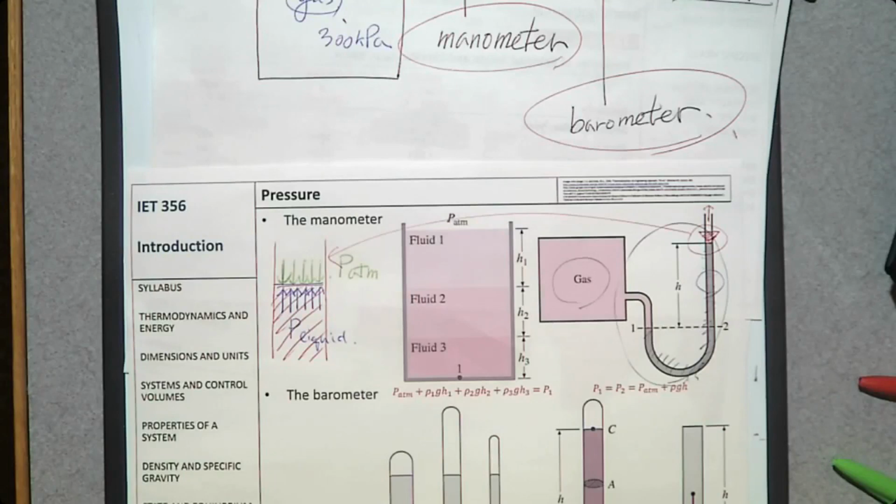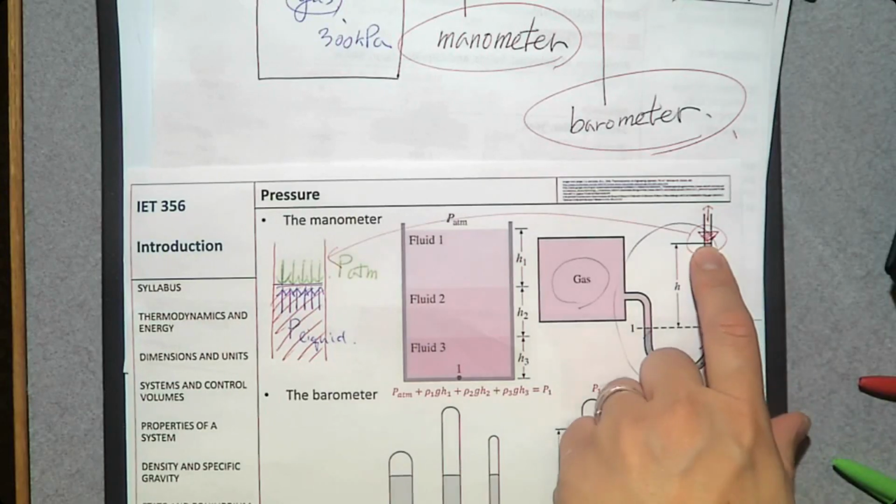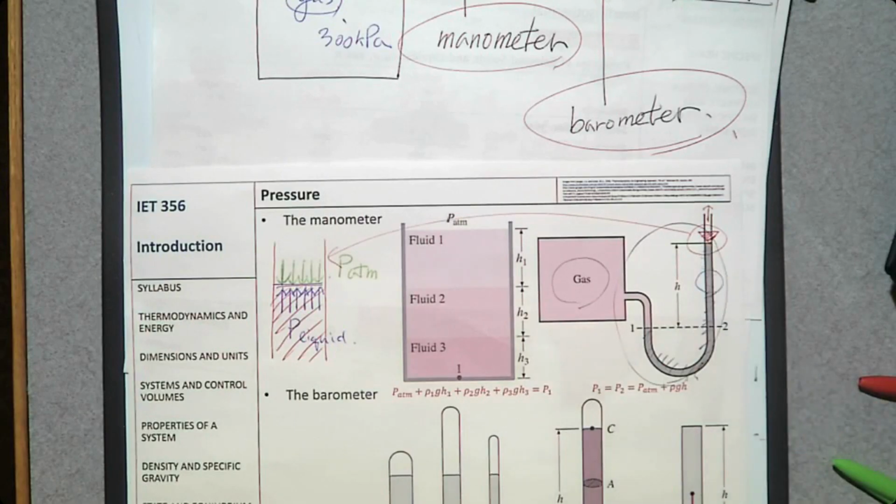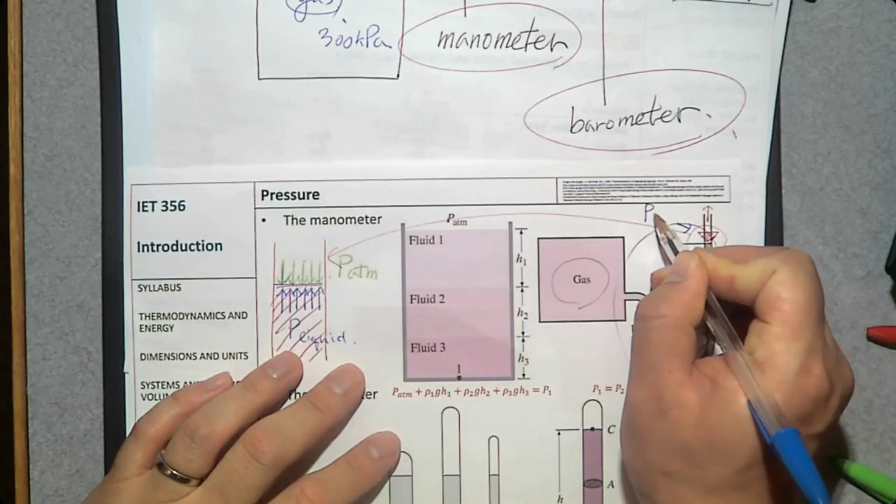If the air pressure is greater than liquid pressure, it moves downward. And if the interface does not move, that means there's a pressure equilibrium, which means that atmospheric pressure and liquid pressure are the same. So if the surface at the end of this manometer does not move, our assumption is that the pressure of this known liquid at this location is atmospheric pressure, P_ATM.